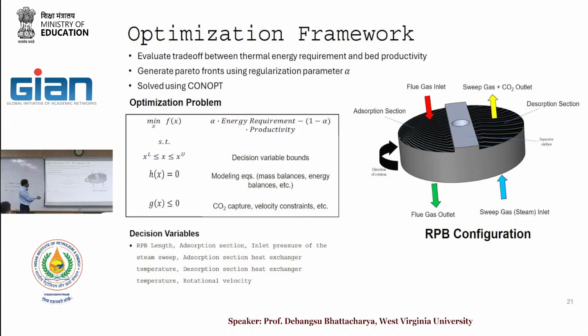But traditionally the flow is in this direction because the seal is along these borders, so you do not need to worry about the seal. But if you are flowing in this direction, then you have to collect it and send it out, and that will be a stagnant location. That makes it tricky to have those seal configurations. But yes, if somebody can come up with a mechanical design, you can have any type of configuration here.